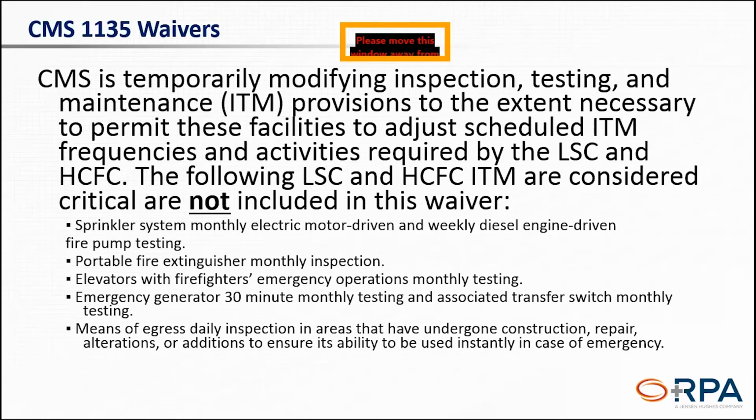We need to continue to test our fire pump weekly or monthly, depending on the type of motor we have. So if we're doing our deadhead churns, we need to make sure we're continuing those. Those were not allowed to be stopped or reduced. Portable monthly fire extinguisher inspections. We need to make sure we're maintaining and continuing those.